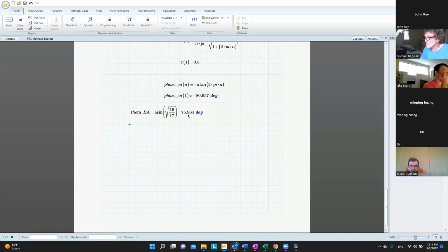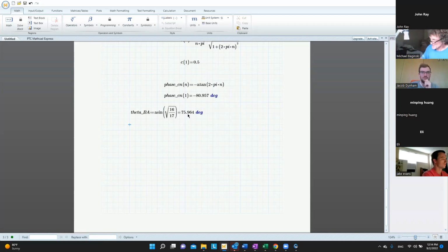All right. Well, what law do we use? Begins with an S. Snell's law. That's right. Snell's law says what? Beta in region 1 times the sine of the incident angle is equal to beta in region 2 times sine of the transmitted angle, or call it T. Well, we already know what this is going to end up with. Beta in region 1 is 1/4 beta in region 2, but I'm going to just write them down there.